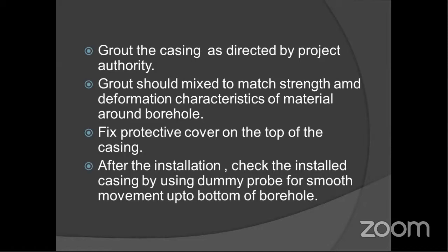After doing the grouting, the main problem we will face is this: as we put the grout throughout the hollow pipe, not in the PVC pipe, that plastic pipe, so as we can see, outside the hollow pipe we are going to put the grout. In this case, the buoyancy force will come to act, and the pipe will start to come up.